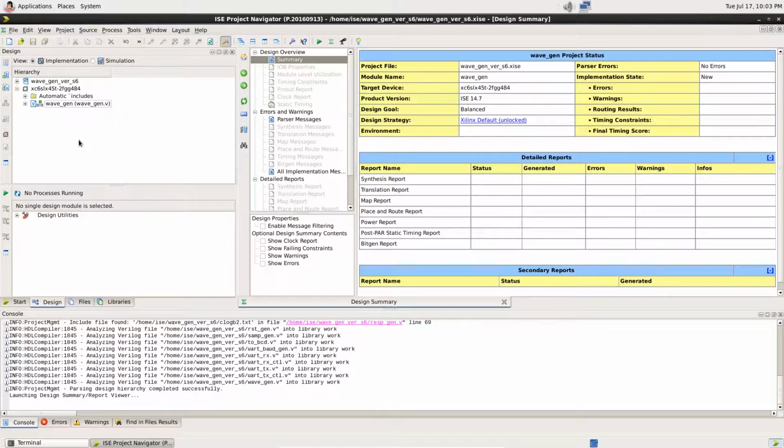Of course, many errors can be caught after synthesis, implementation, or in lab, but that requires long iterations to identify an issue, trace that to a root cause, correct the code, and then rerun all implementation phases again. Linting and CDC tools like Aldec's ALINT-PRO could be useful to prevent mistakes in early design stages.